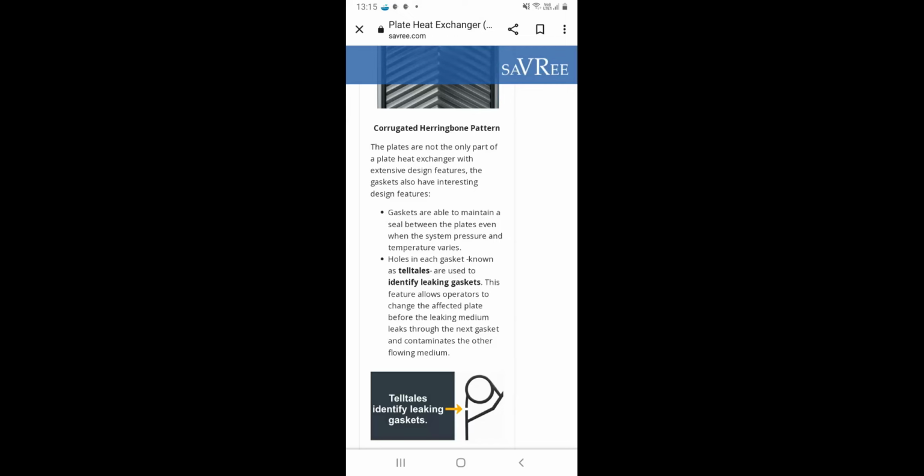What type of material will you use for the plug? The same as the tube material, not Teflon or anything else. Make it either brass or the tube type material, because the plug material is the same as the tube, and that is provided by your manufacturer.